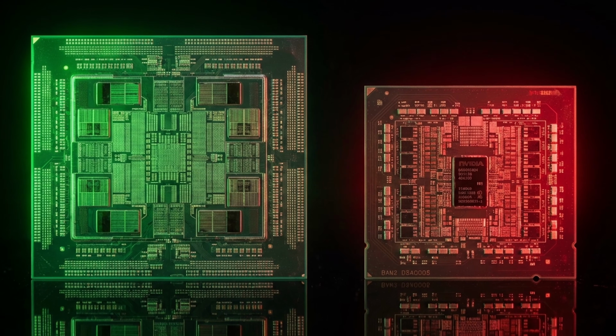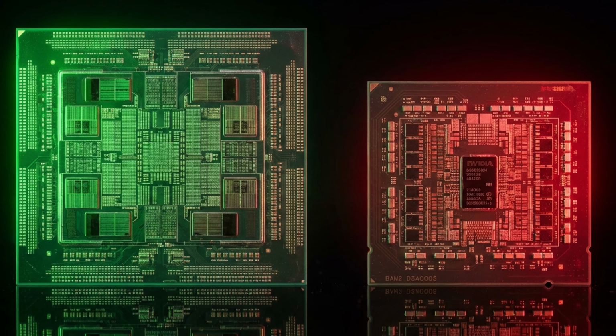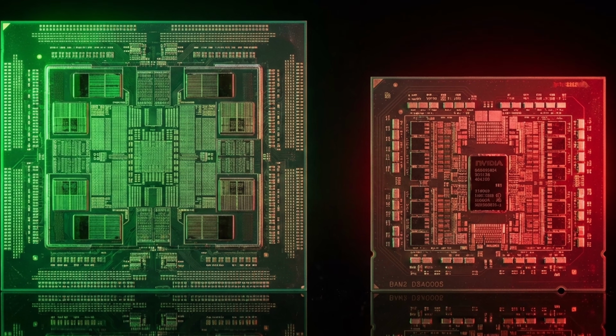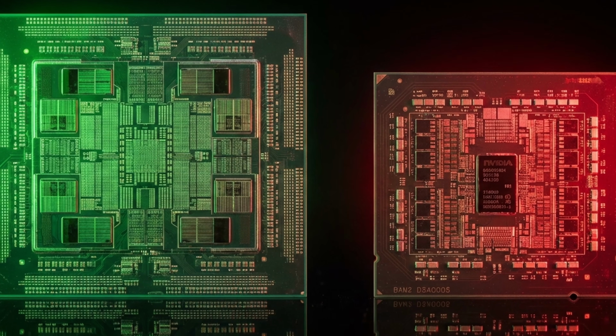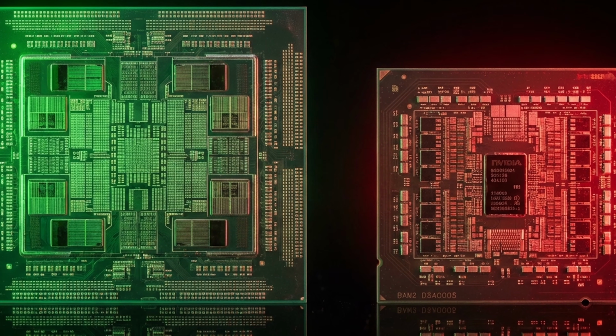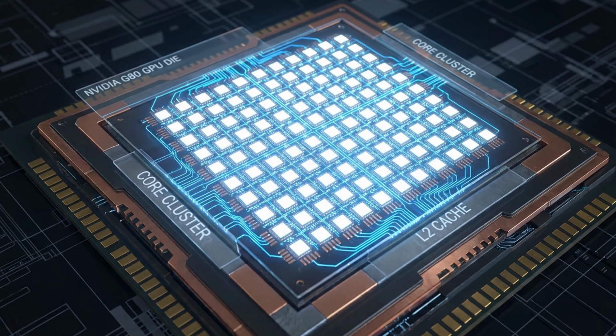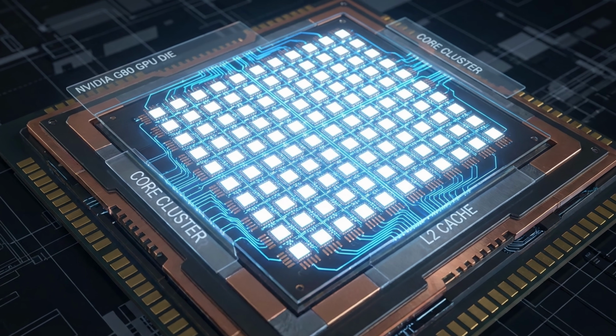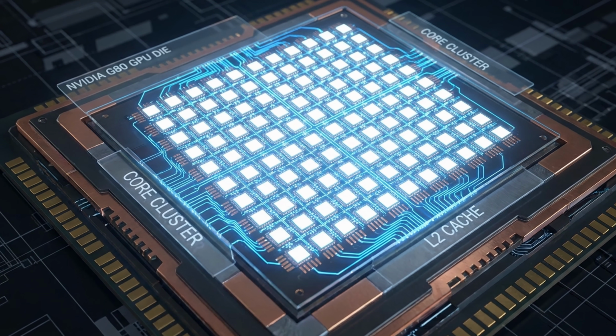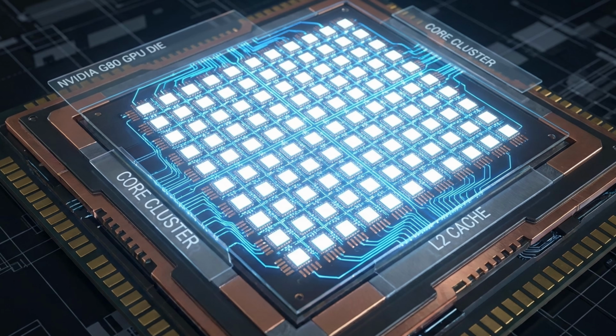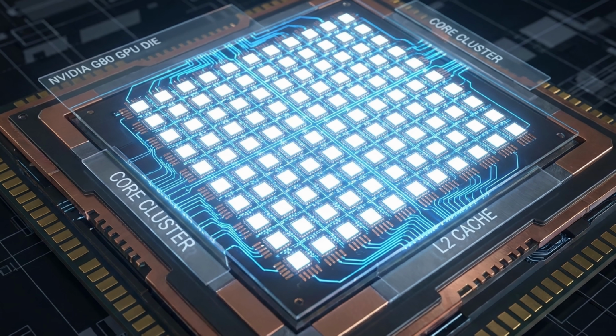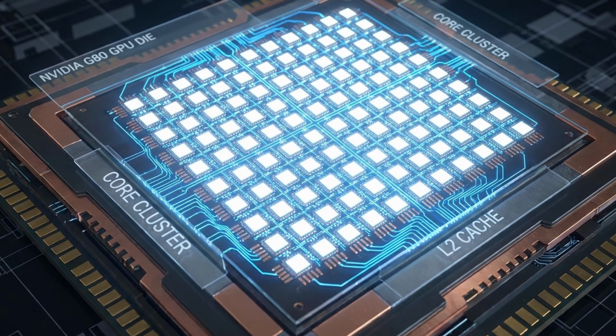While both major manufacturers embraced this unified philosophy to comply with DirectX 10, their hardware designs differed significantly. NVIDIA's G80 architecture utilized a highly efficient scalar processor design, clocking its individual stream processors at incredibly high frequencies independent of the rest of the chip.